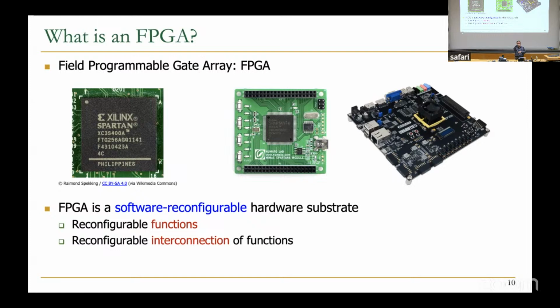You have a lot of switches that they call switch box and connection box, and all these switches can be reconfigured in order to connect a logic block to another logic block, which is very important for an FPGA to implement your circuit. And also we have reconfigurable input and output in an FPGA.